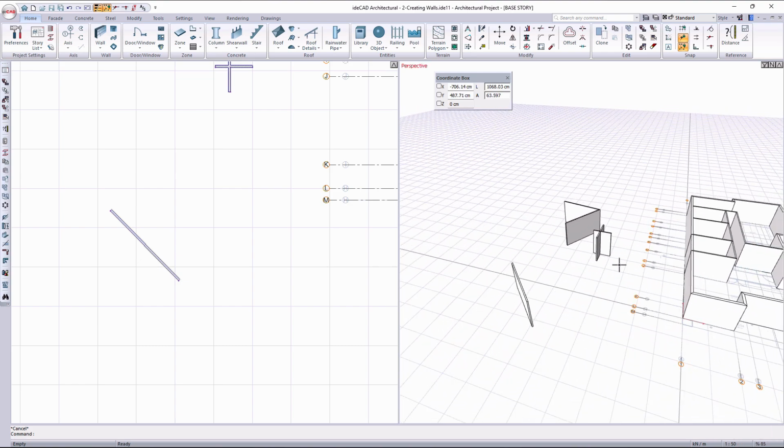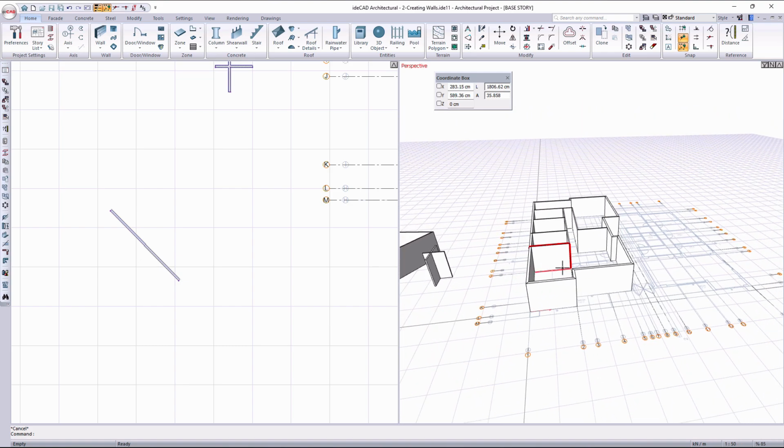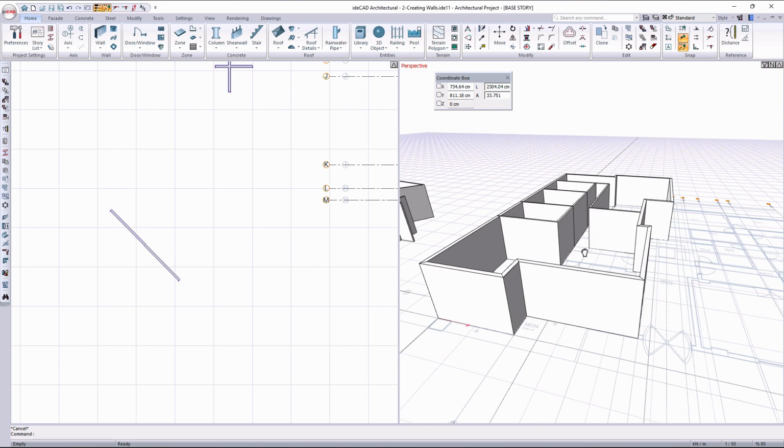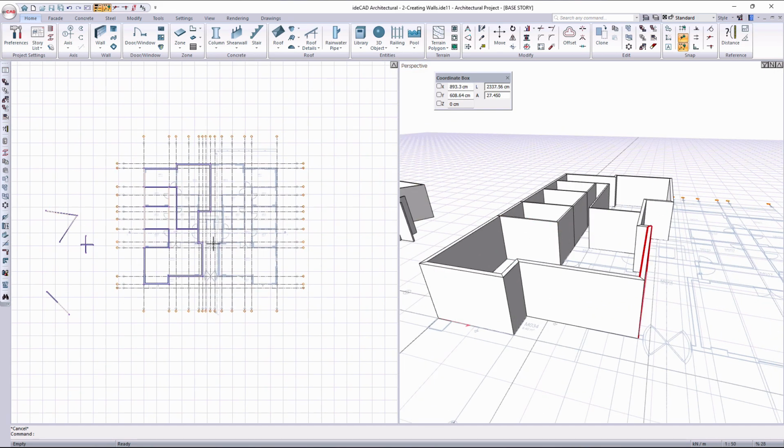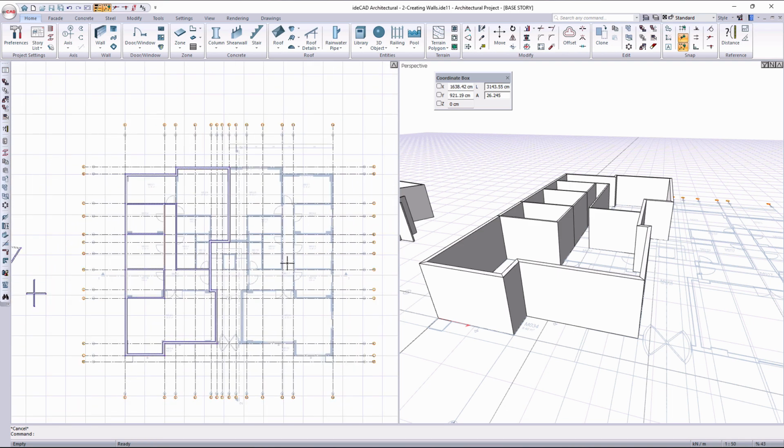With the Select Similar command, you can quickly select multiple objects that share the same properties, especially useful during the modeling process. You can group objects like walls, beams, and others based on criteria such as material, dimensions, or other attributes. If you use the command in the plan view, only the relevant objects on the active story will be selected. If you use it in the perspective view, it will select the relevant objects present in the 3D model shown in that view.